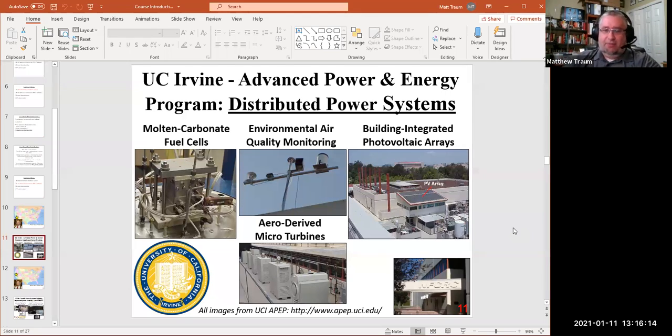And so if you have a solar array, in order for a solar array to run a bank of lights, you first have to invert and then rectify the current. And every time you change the form of the current, from DC to AC to DC, there's an efficiency loss in that process. And so Next Tech's value proposition was to eliminate the inversion and rectification steps and take the solar generated electrons as direct current and pipe them directly to the lights.